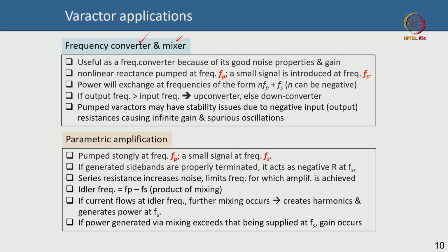What do I mean? You have a pump frequency of fp, that is the signal at which you are pumping the varactor, you are bringing the signal. You are also introducing a signal of a smaller magnitude, a smaller amplitude, at a frequency of fs.